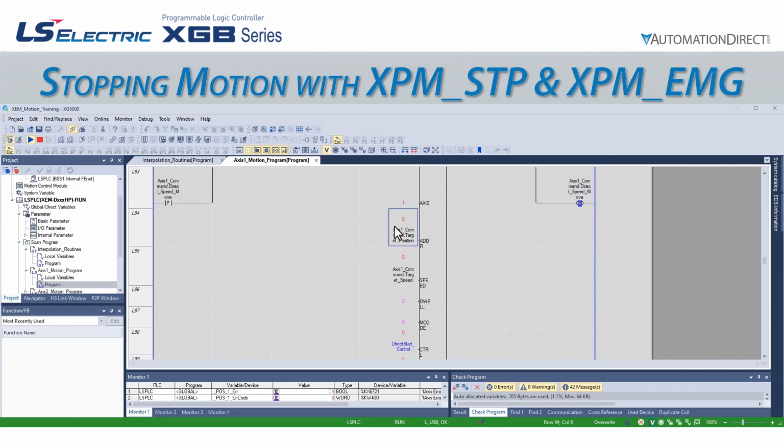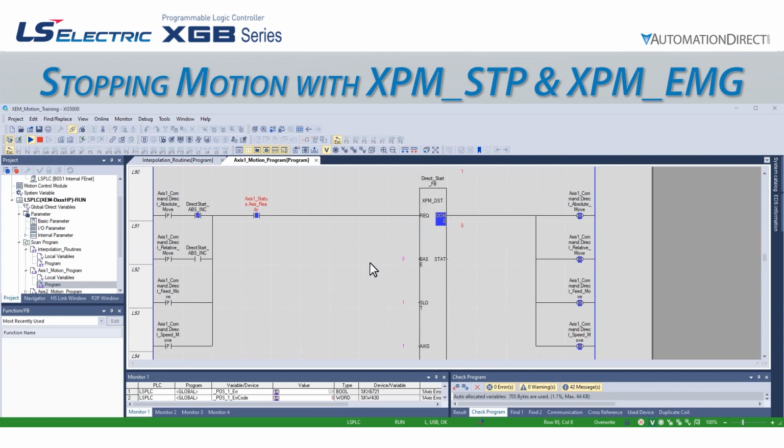Let's set our target position to 50,000 and our speed to 1,000. This will give us a longer move that we can interrupt with the decelerating stop and emergency stop commands. Let's set up our monitoring for this move as well.